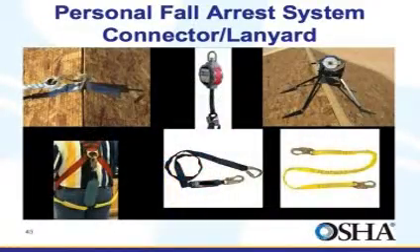Lanyards should have a minimum breaking strength of 5,000 pounds. Self-retracting lifelines and lanyards, which automatically limit free fall distance to 2 feet or less, shall be capable of sustaining a minimum load of 3,000 pounds in the fully extended position.